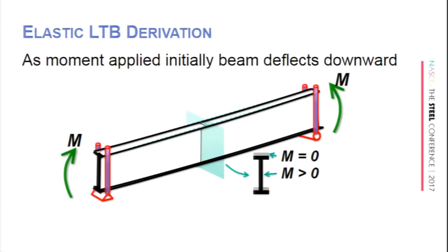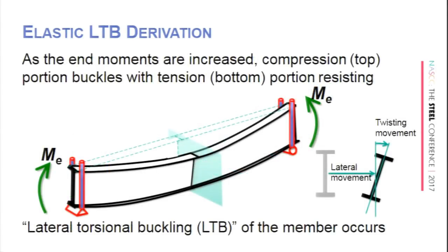So as we load this beam, it's going to just deflect downward vertically. It's going to eventually reach a point because there's no other bracing besides at the end, and our unbraced length is L sub B. Okay? And let's say for this particular beam, we don't know what L sub B is, or whether L sub B is greater than or less than LR, LP, LPD? We don't know that. So we're making the assumption that as we load this beam, eventually that top flange is going to want to buckle laterally, just sort of like minor axis bending of a plate.